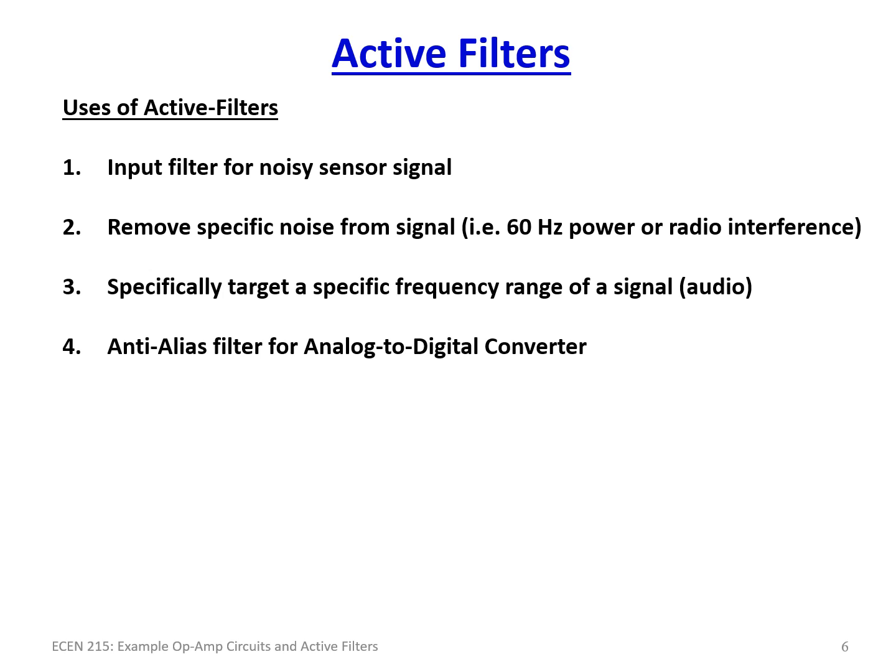As such, if your frequency of sampling the data happens to be, say, 1,000 hertz, in other words, you're sampling the input signal at 1,000 hertz, then you're going to want to make sure that whatever signal is coming in is no faster than about 500 hertz.